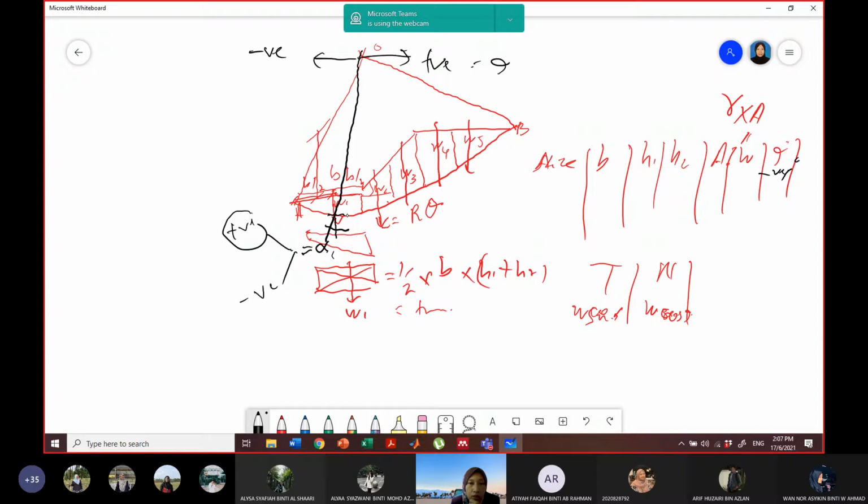And then if you locate alpha for W3, this alpha is positive. For example, for slice number 3, you can have positive 5 degrees. After you have confirmed all these inputs, then you need to know how to calculate the circular length of the arc AB. As I said again, L_AB is equal to R theta. For example, R is known by numbers, and then theta.